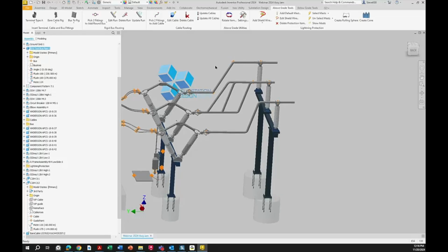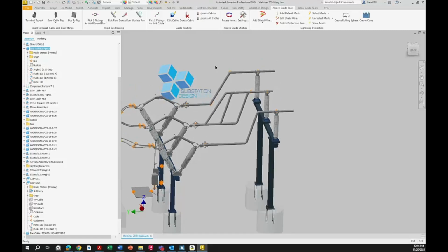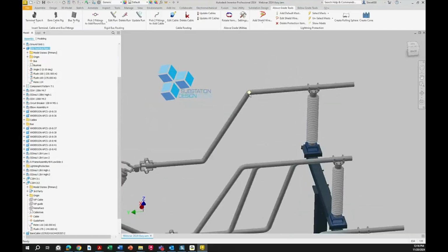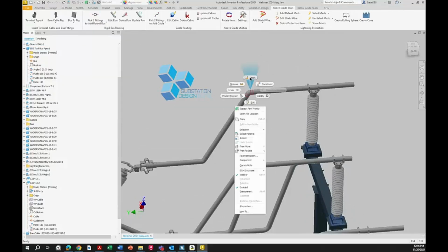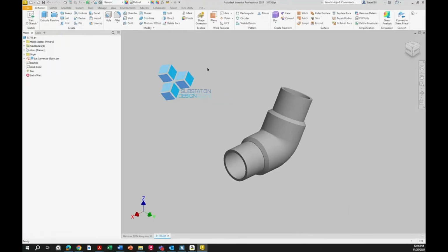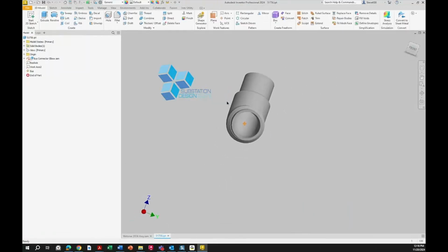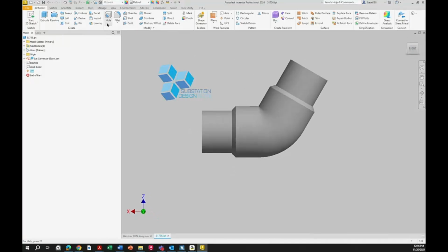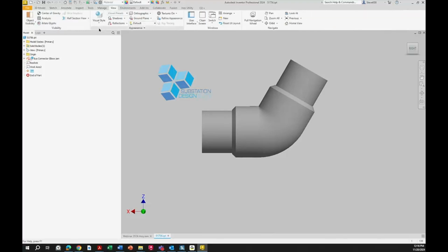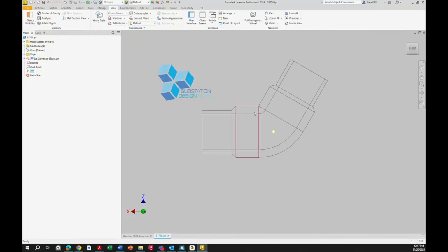If, on the other hand, I am using fittings to place that bus, let's look at this one here. You can see I got an elbow fitting here. Let's change this. You see I have an elbow fitting here. And what I'm doing now, I am constraining, I'm bringing my bus into that work point, right? And if you look at that work point, we look at a plan, a profile, change our view. You can see where that point is. It's at the equal distance between the column here coming down and the tube here coming down. So that's the equal distance.